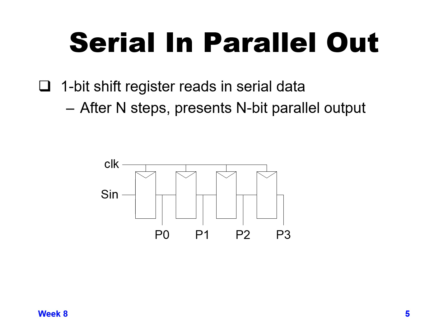So here we have the concept of a serial in, parallel out. This is just showing a single bit. So a 1-bit shift register that is a 4-bit input serial in. So we take 4 cycles to read in the serial data. And so 1 cycle at a time, we're reading in 4 separate cycles worth of data.